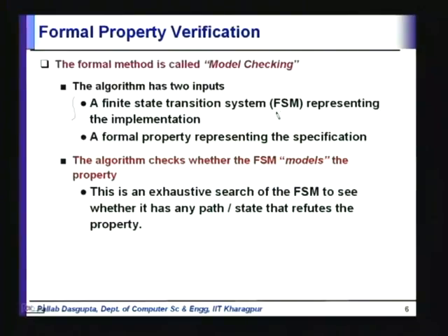What hurts you is the size of this FSM. Okay. And remember, the size of this FSM is exponential in the size of the circuit. Right. So, if you have a k bit register, the size of the state space is 2 to the power k. Alright. This is where it hurts us, not in the algorithm.